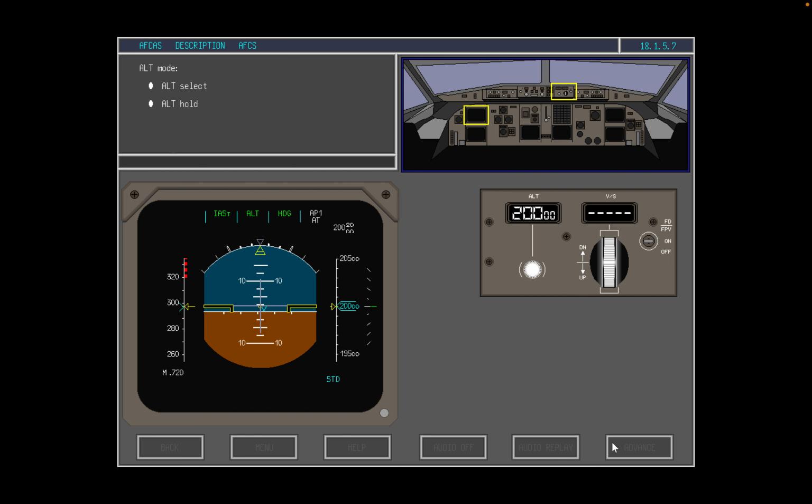The altitude control has two modes, altitude select and altitude hold. Altitude selections and pre-selections are made by rotating the altitude knob on the flight mode panel. Rotating the altitude select knob in altitude hold pre-selects a new altitude at the flight mode panel. The pre-selection is shown in the FMP window and by the blue ALT in the FMA path window.